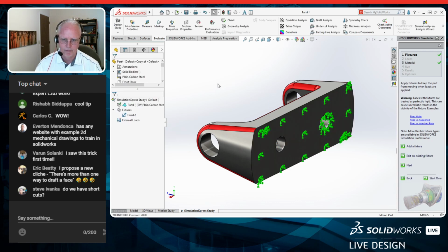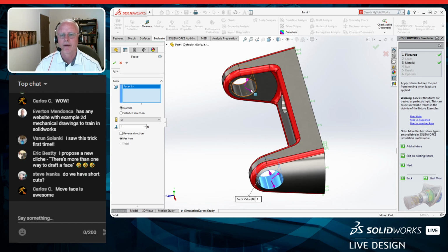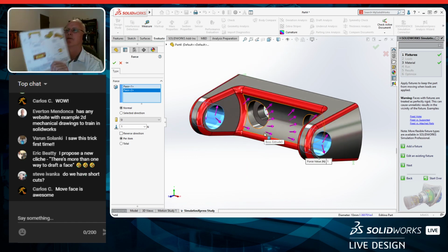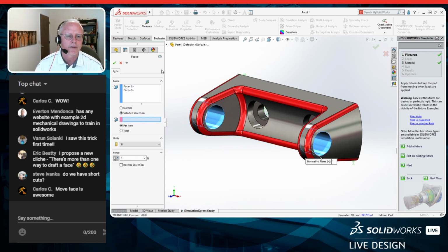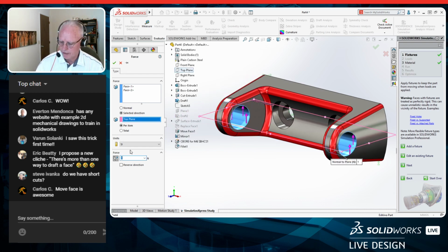And actually, we won't do that yet. I'm going to add my force. I'm going to add a force onto this face and onto this face. And I'm looking at my sheet here. I didn't refer back to that, but that's what it's telling me to do. Add 1,000 Newtons in a direction that is this way. 1,000 Newtons, and that's per item. So my total is going to be 2,000. So be careful when you're doing this. Make sure you're applying it either as the total force or per item, so that those are the items that are selected there.